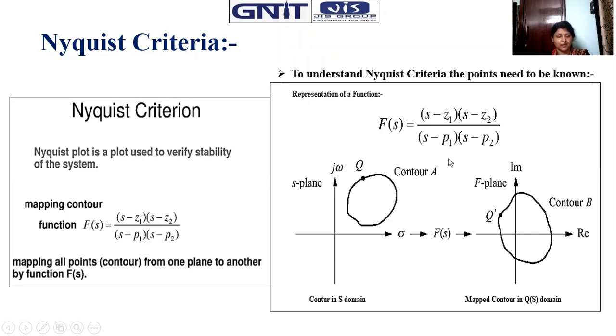Okay, keep it in mind. Closed loop. So here, if there is any closed loop pole on the right hand side, right part of the plane, the system will be unstable, obviously, right? If it is a right hand side pole, then the system will be unstable. If it is a left hand side pole, then the system will be absolutely stable, right? So in this way, our objective is to encounter basically the right hand side pole positions.